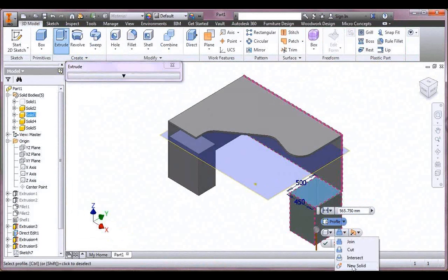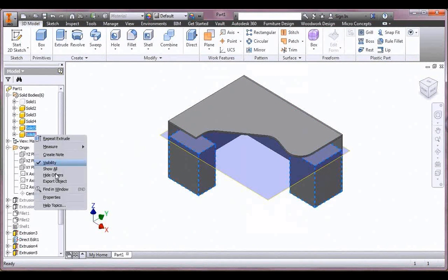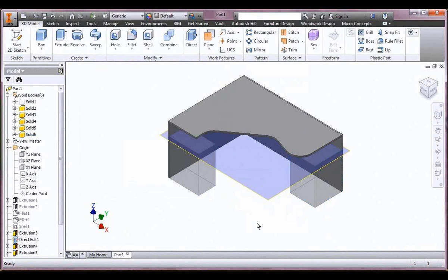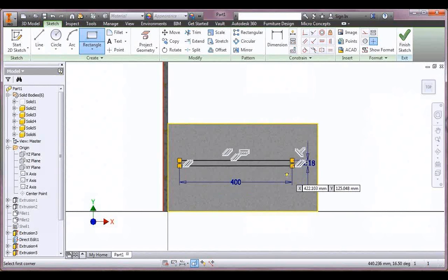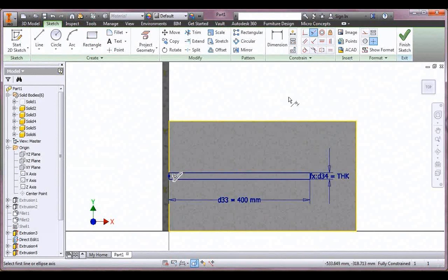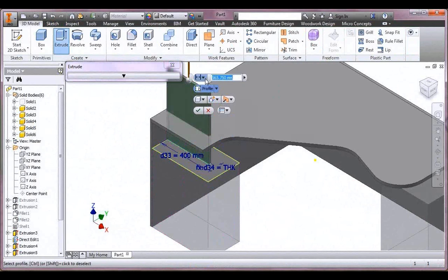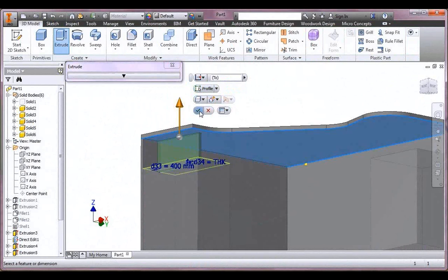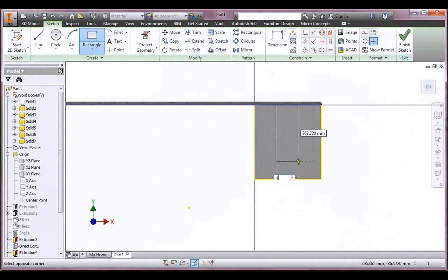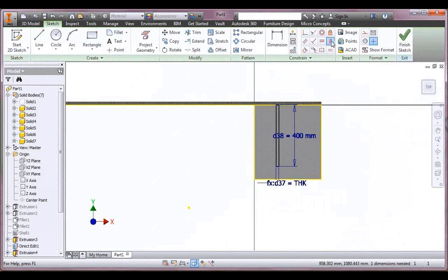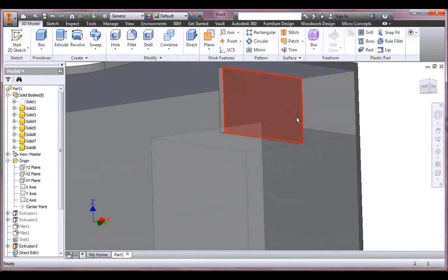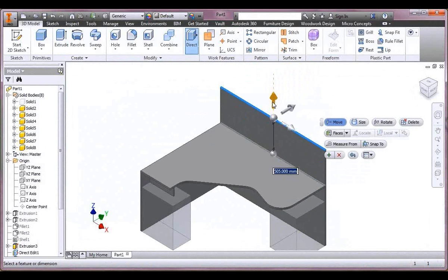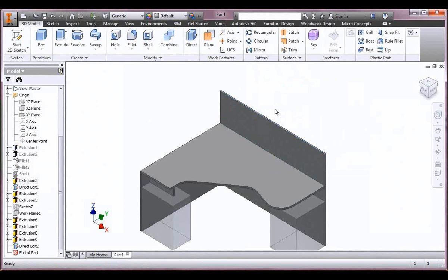So let's put in the final one, which will be the cabinet with the drawers. We'll just place that in there. And I'm going to change the actual material colour to a polycarbonate clear there. Now I'm just going to drop in a simple support. I need to support the top of the desk to the underside of the actual desktop. I'm using some tools here to constrain and make sure things are aligned centrally. It's good practice to keep things centered up, but you're not limited to doing it that way. You can see straight away I've drawn that sketch of that rectangle, sized it, and then literally extruded it to the next face, the underside face of that particular panel. And remember, if I change the work plane of the height of the box, then it will actually update automatically.